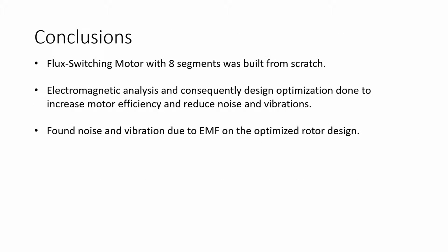We've almost come to the end of this presentation. So in conclusion, I'd like to tell you that we built a flux switching motor with 8 segments from scratch. Electromagnetic analysis, and consequently design optimization, was done on it to increase its efficiency and to reduce noise and vibrations. We also, in the end, found out the noise and vibration due to EMF on the optimized rotor design.